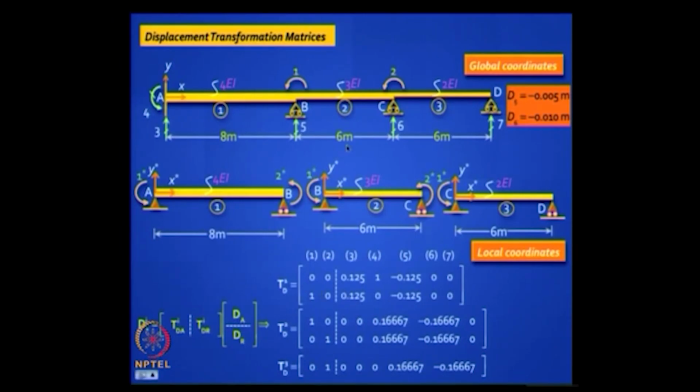If I apply D1 equal to 1 here, you agree that, well, we have two elements here, one is the element in the matrix and you have the actual beam element, okay. So when I say element, I am referring to the element in the matrix. The second element in the first beam element will be 1 and the first element in the second beam element will be 1 and the rest will be 0, clear.